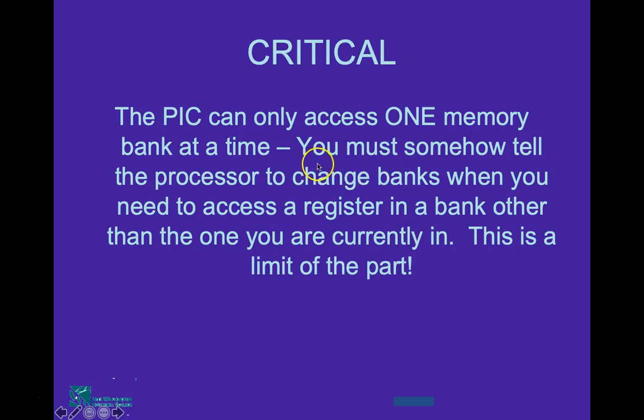So this is the same thing. You must somehow tell the processor to change banks when you need to access a register in a bank other than the one you are currently in. So this is a limit of the part.